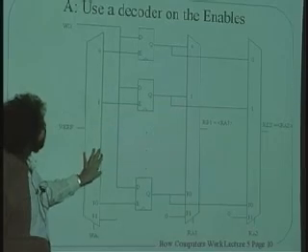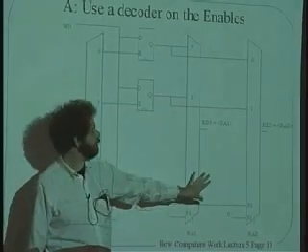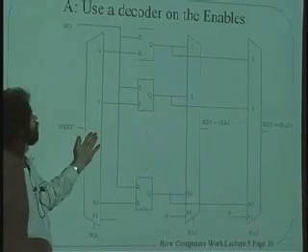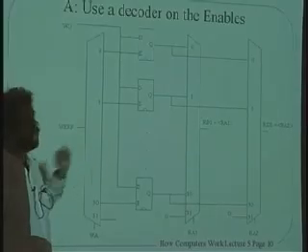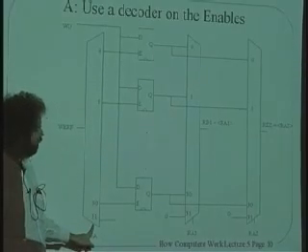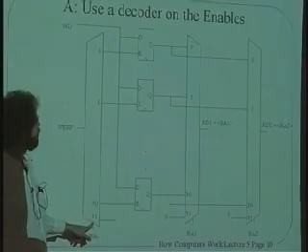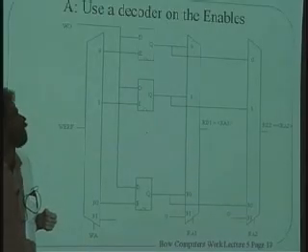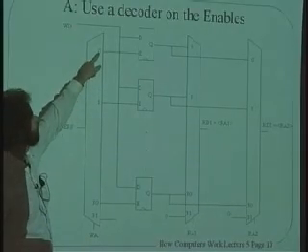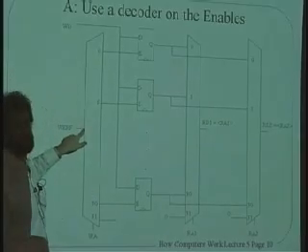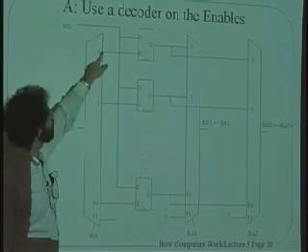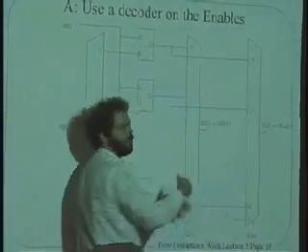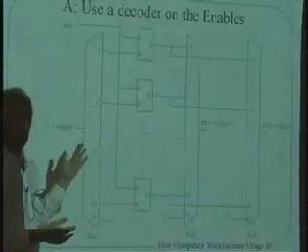And this device over here looks just like this one over here, except this is a selector, and this is kind of the mirror image of that. And guess what this is called? This is called a decoder. Okay, and what it does is it decodes an input here, which is 5 bits wide, and it figures out which combination of 5 bits those are, of the 32 possible combinations there are. And if the combination is 0, it steers this signal over here up to 0, in the same way that if RA1 is 0, it steered the 0 over here all the way down to here. So it kind of works the same way, but backwards. Okay?